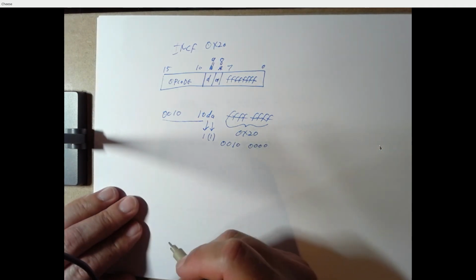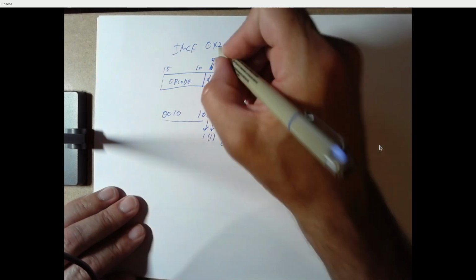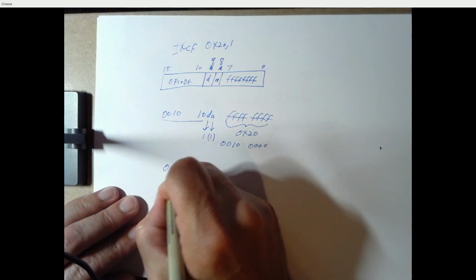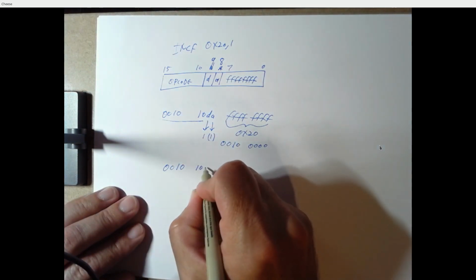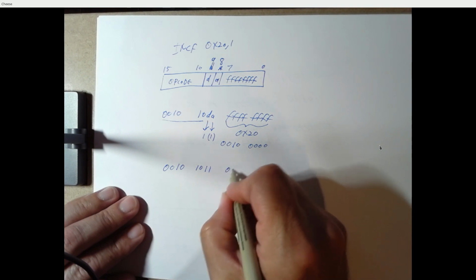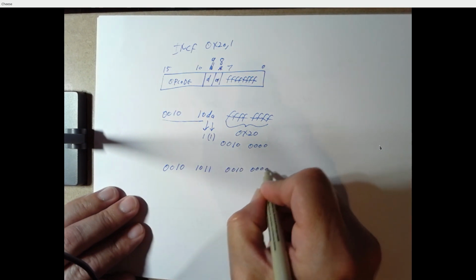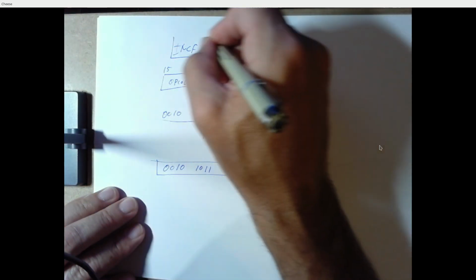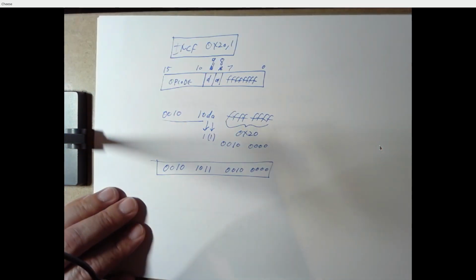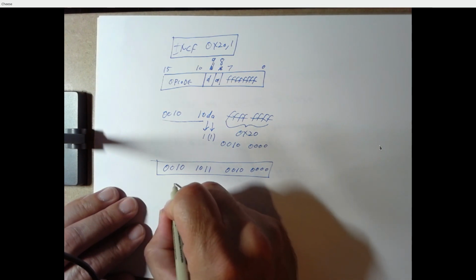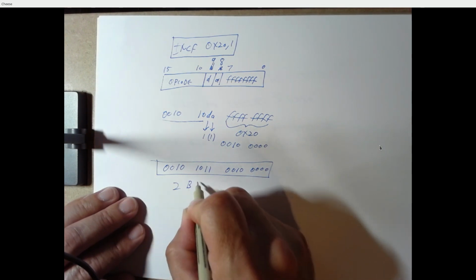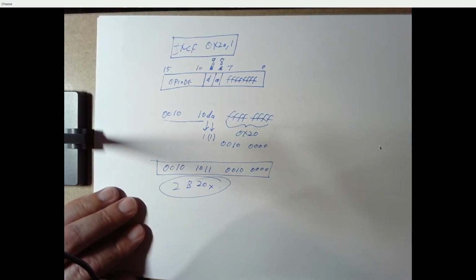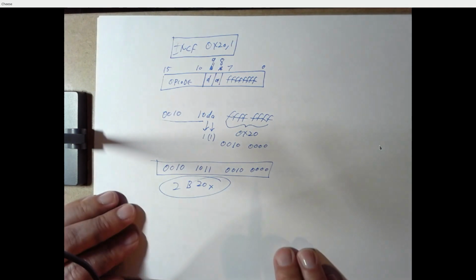So the full binary coding for increment file register 20, where you implicitly said destination bit of 1, is the following: 00101011 00100000. That's the 16 bits corresponding to this instruction. And since binary for humans is error prone, we usually write this in hex. This would be a 2, a B, a 2, and a 0. There's the 4 hex digit number corresponding to this opcode and this operand.